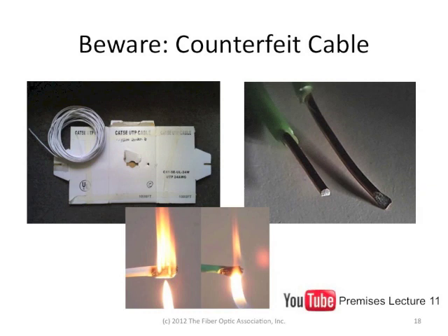Anything in a plain, unbranded box is suspect. We've seen Category 5 cable that's not copper, but is aluminum cable coated with copper. A lot of the cable jackets on both fiber and copper cables that are counterfeit are highly flammable and extremely dangerous. Make sure you know who you're buying your cable from and who manufactured it.